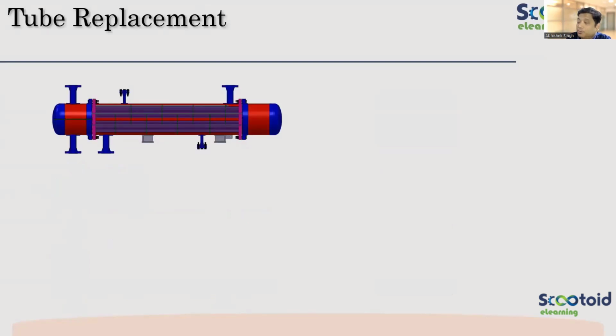Okay. Now, tube replacement. If I have to replace a tube, it many times happens when we take the plant for maintenance, we evaluate. If there is some failure in the tubes, if let us say they are leaking, I can remove the tubes during maintenance. Okay. So can I do that in fixed type heat exchanger, BEM type? Can I replace the tubes?